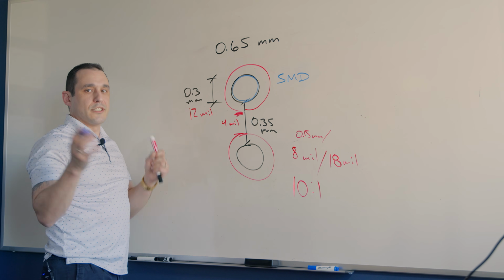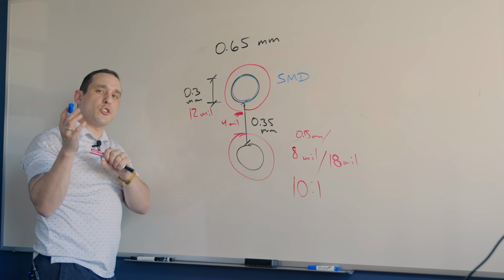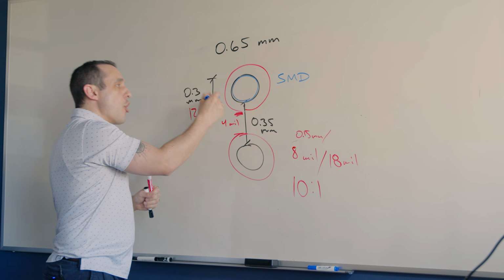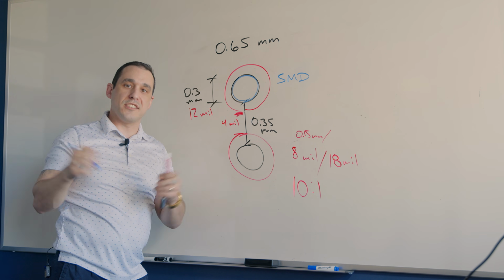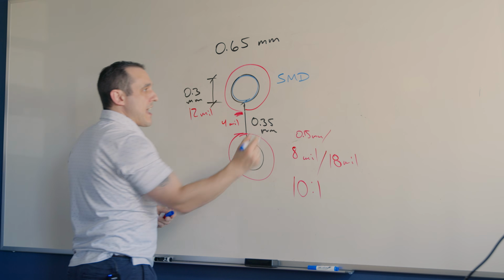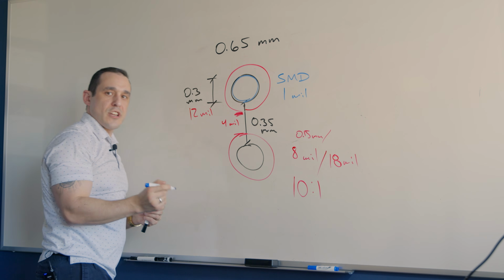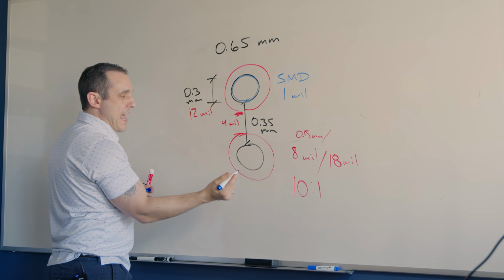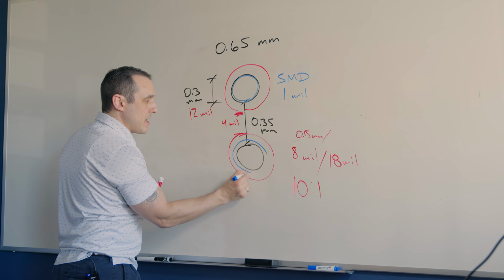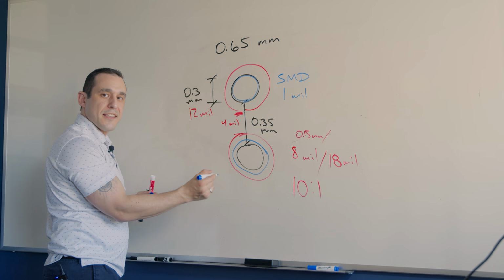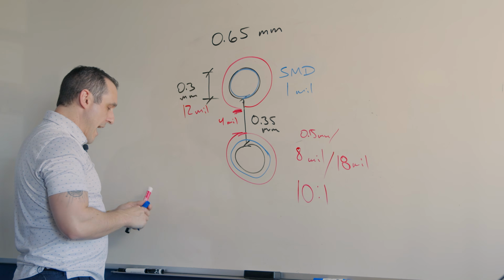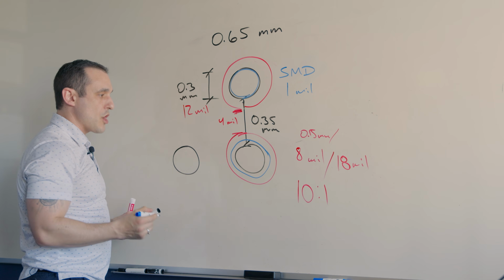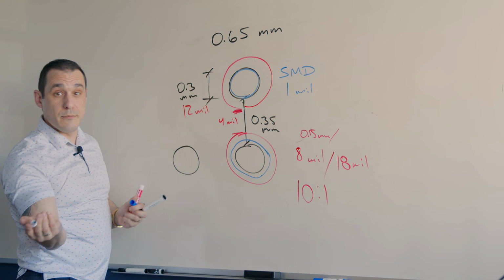Now this is typically why in a lot of footprints for fine pitch BGAs, you can't actually just apply your global solder mask opening rule in your CAD tool. It's going to oversize some of these pads compared to other pads in the BGA footprint. For example, if we had a 1 mil solder mask expansion as a global rule in the entire BGA footprint, then any footprints that had via in pad would have a solder mask opening that is just a little bit larger than these other pads that don't have any vias in them. So if I have a pad over here, let's say, it's going to have 0.3 millimeters or 12 mil of exposed copper, whereas this pad will have 14 mil of exposed copper.